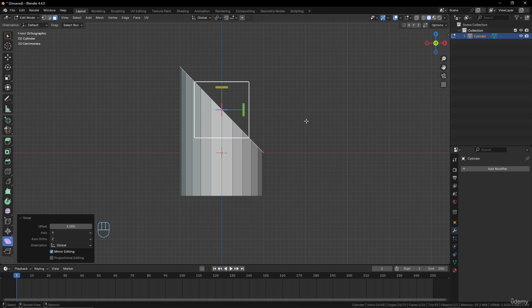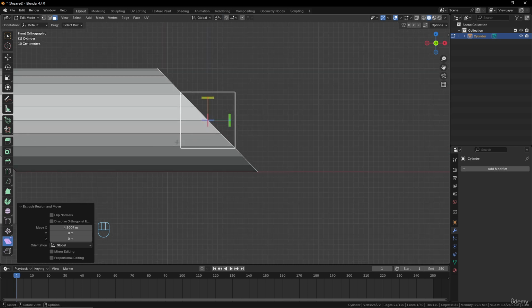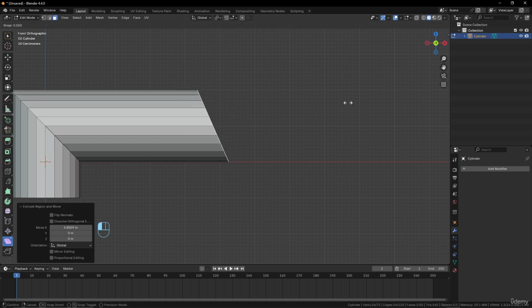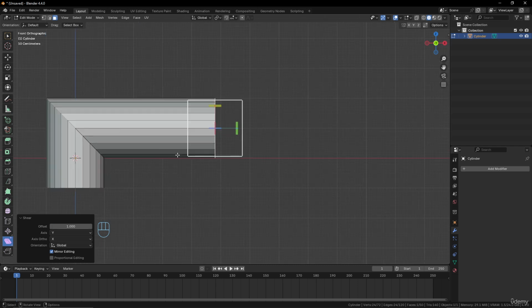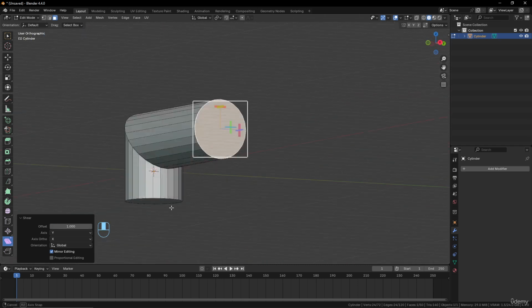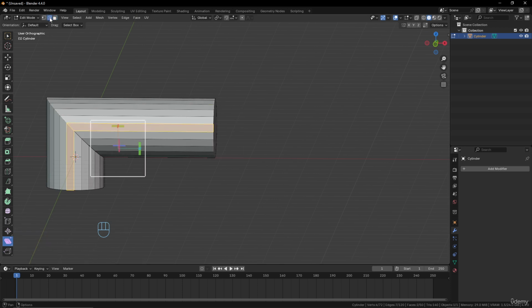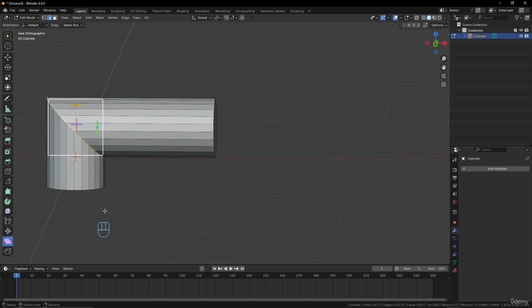And at that point, what is good is that I can extrude into the x-axis, and now I have a corner that is perfect, okay? Now I can put it back by doing the same way, not this way, but that way, okay? And here I come back to 1 and it will give me the perfect shape I want, okay? So it can be useful sometimes to make some right shapes here. And with this loop now, with Control B, you can make a bevel or something that is smoother, okay? So yeah, these tools are always useful.